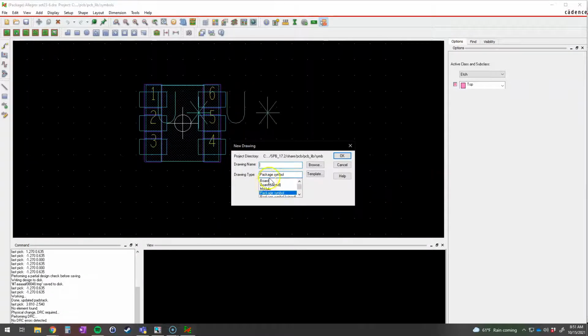So I'm going to scroll up here. There's board and board wizard. We're going to use the board wizard predominantly. The board is definitely for more custom types of boards, if you have specific kinds of shapes that you need the board to be in, or it lets you set up all of the design constraints manually as opposed to somewhat automatic here. But we're going to go ahead and use the board wizard.